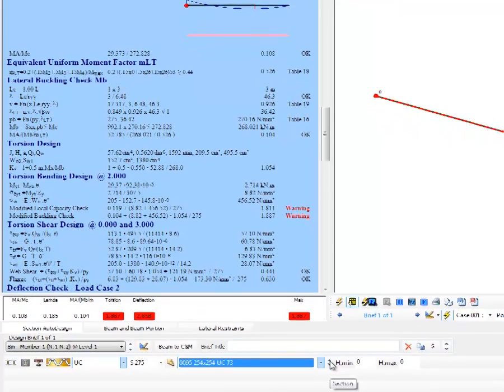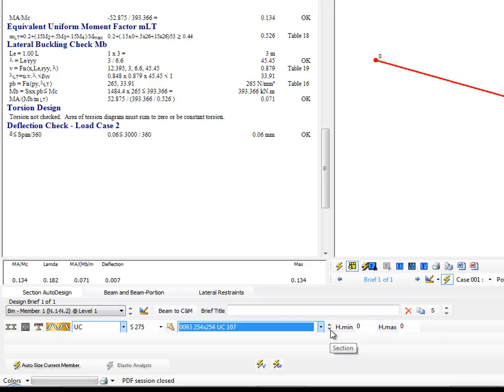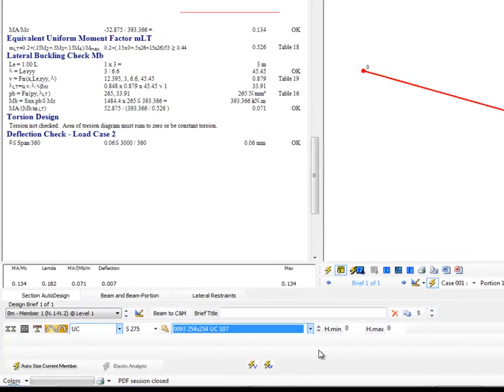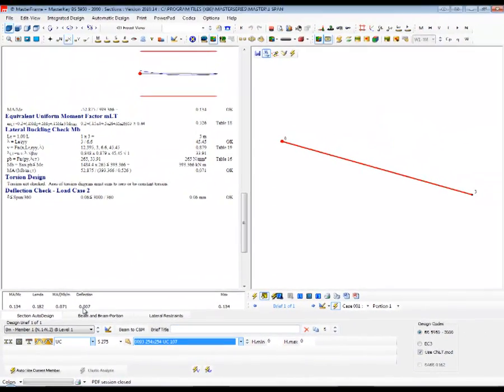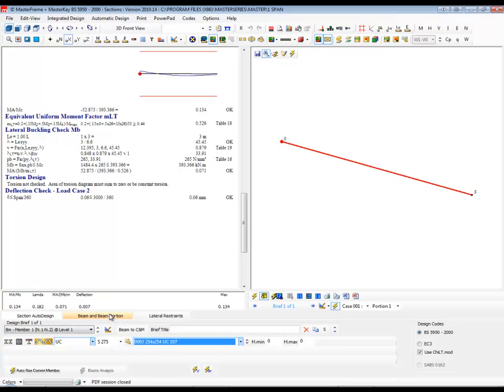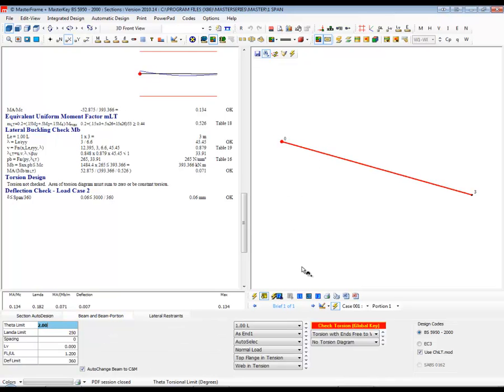So in an open section we would need nearly 80% more material to resist that, and we're getting a far bigger degree of torsion. So that's your free steel design for unusual things, because I put a spring torque in. I could have put a spring settlement in as well, but obviously it is only single spans.